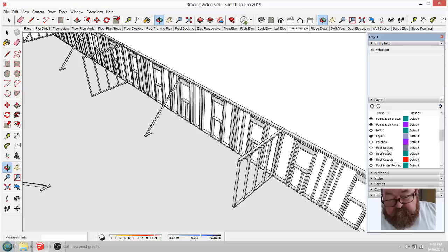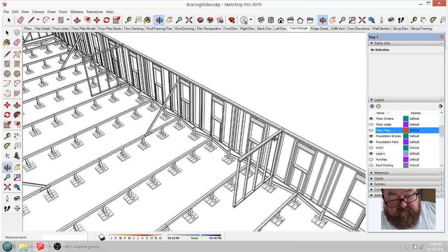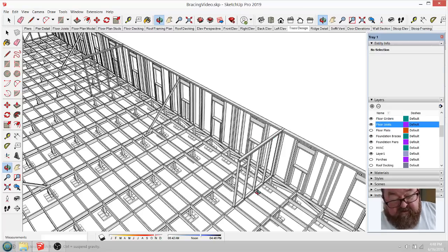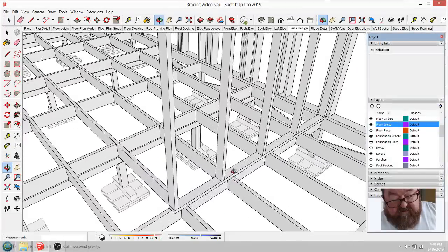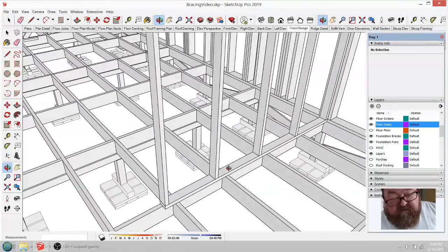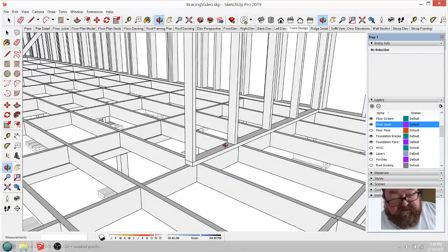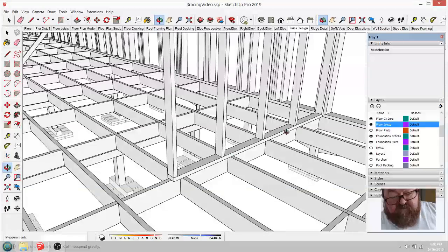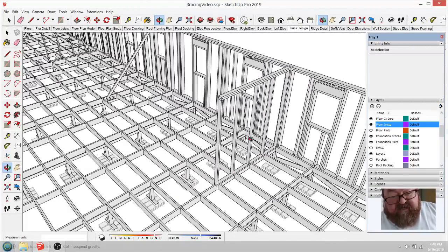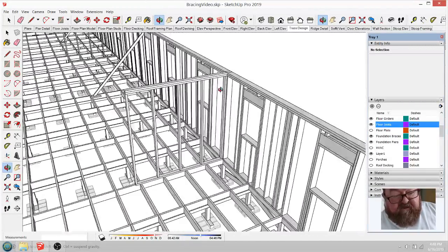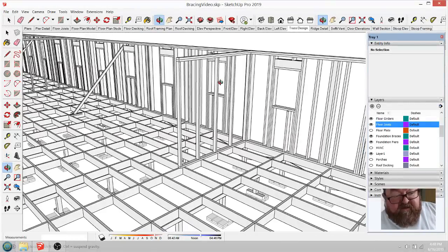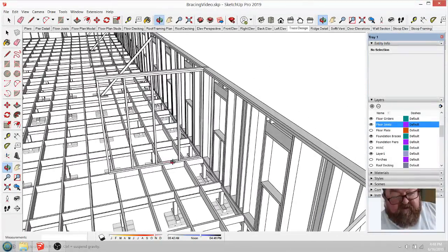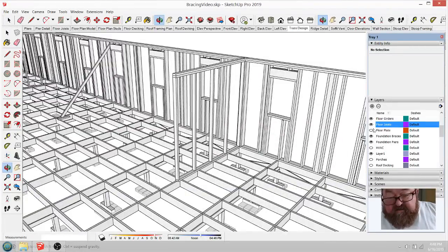The floor plate, and turn the floor joist back on. These walls, now that just worked out pretty good, but these walls need to be securely secured to the floor framing, because the whole point of these is that you're taking the lateral load of a wind load, and you're transferring it down at that angle to the floor. Okay, that's going to resist it.